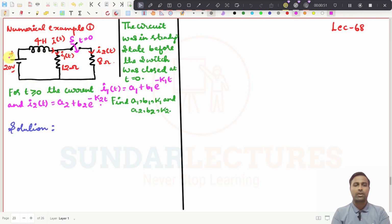See, this is the given network. A voltage source is connected, and then an inductor and a resistor. There is a switch, and that switch is connected with the 8 ohm resistor. What are the given conditions? The circuit was in steady state before the switch was closed at t equal to 0. Which means before closing the switch, this circuit was at steady state. The voltage source, inductor and resistor were connected for a stipulated time, and that is what they have given as the steady state condition.